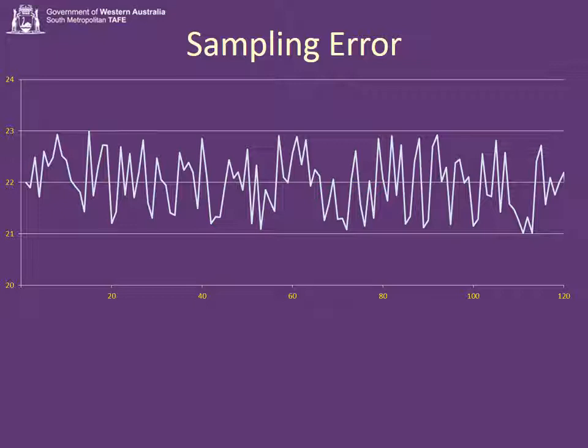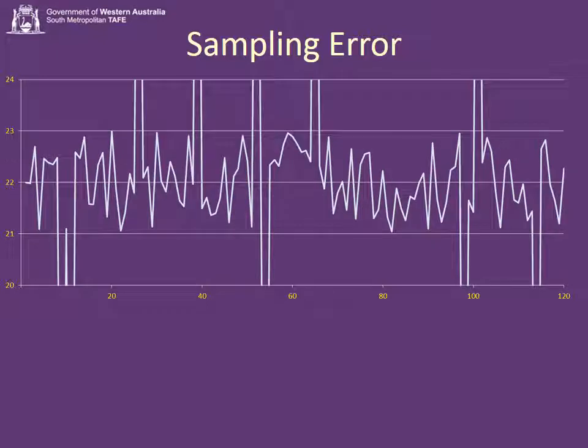Now, that's fine, except for when we ran the cable, we ran it past a fluoro. And that fluoro just happens to be flickering today. So we're getting some spurious readings. And those spurious readings are looking like that. Now, what's happening is that when it flickers, the temperature's either going to 0 degrees or it's going up to something ridiculous.